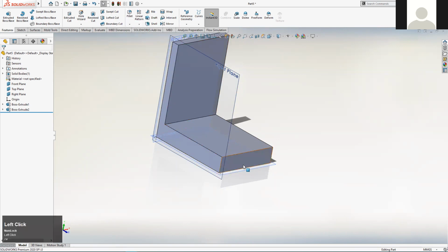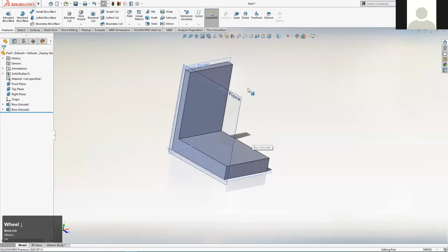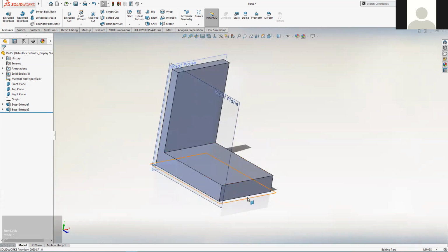It tends to happen in a lot of cases, such as when we're adding our own user relations into sketches. It does a similar thing. If you select an edge and a point in a sketch, it gives you some quick access icons to do with the relations that you can add to those two things that you've clicked on. So yeah, you may as well take advantage, is the thing to take away. You may as well take advantage of all the time-saving tools that they've put into SolidWorks.